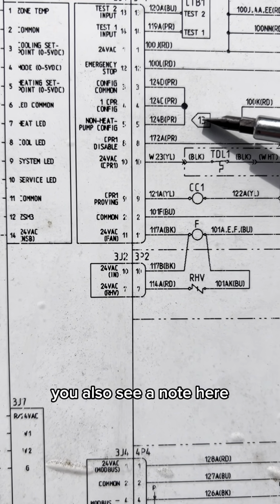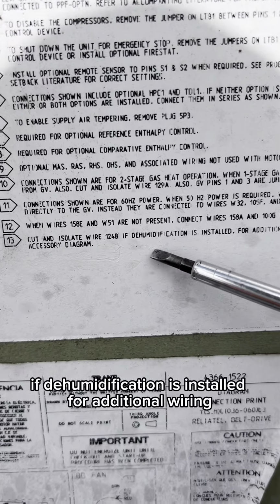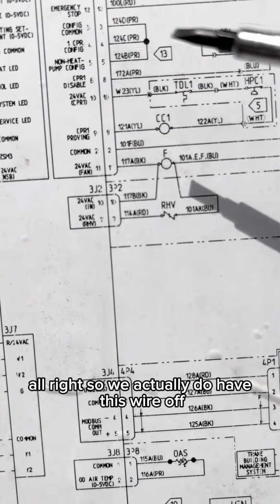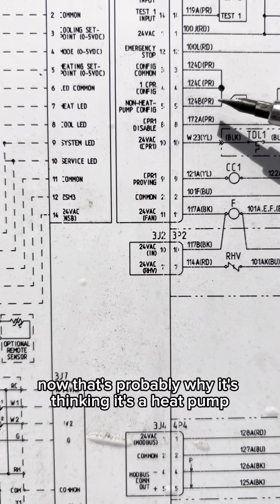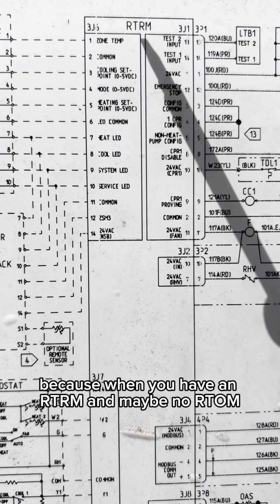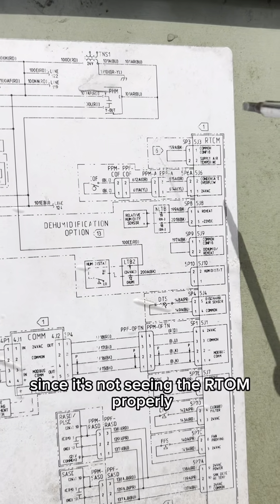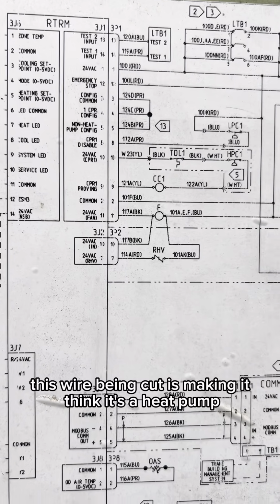You also see a note here, 13. And it does say down here, cut and isolate wire 124B if dehumidification is installed, for additional wiring, see, blah, blah, blah. All right, so we actually do have this wire off. Now, that's probably why it's thinking it's a heat pump, because when you have an RTRM and maybe no RTOM, since it's not seeing the RTOM properly, this wire being cut is making it think it's a heat pump.